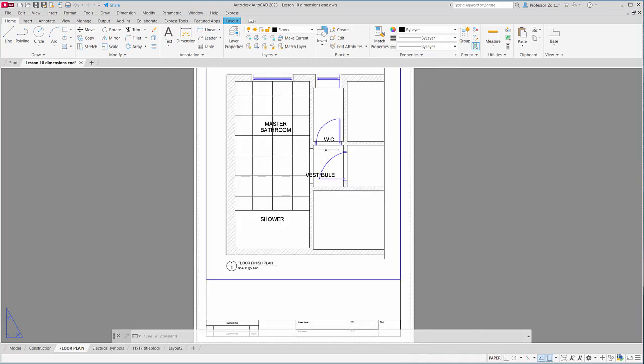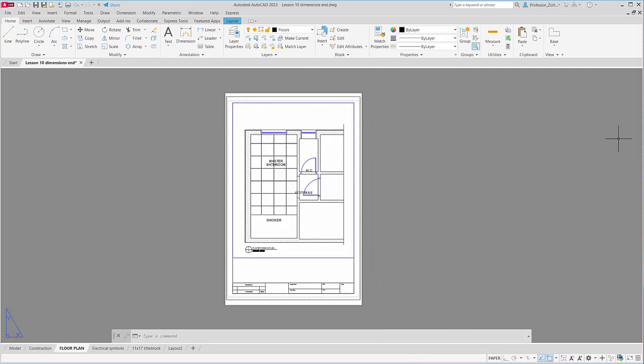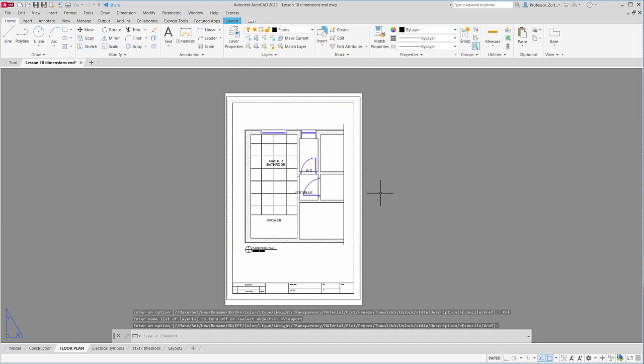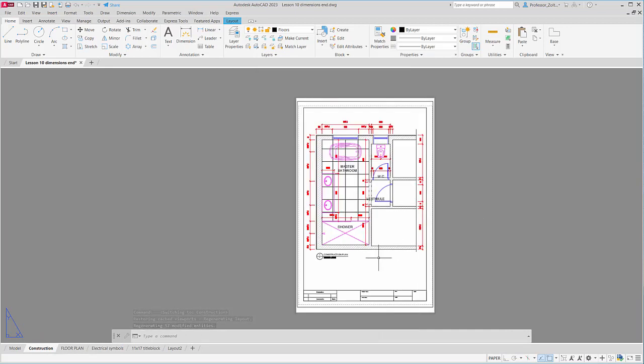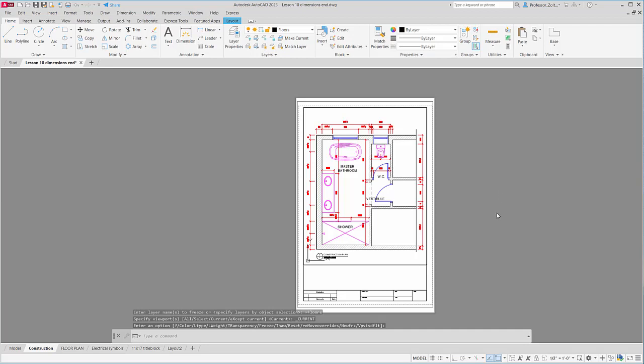So now I'm just going to zoom out. And once I have all the tiling in place, make sure you turn off the viewport layer. And that's a universal application. So on each of these projects, the viewport will be turned off. Now, moving to the construction project, I've got my floors on. So I'll double click inside, go into my floors viewport, turn that off. Make sure that's what I want to see.